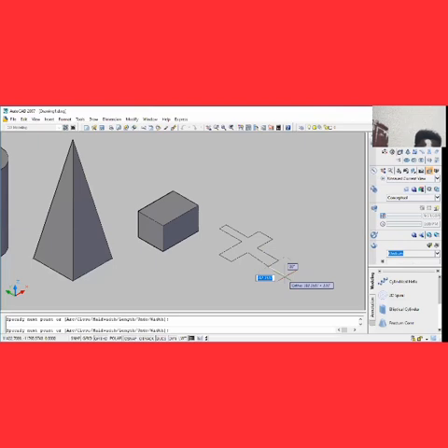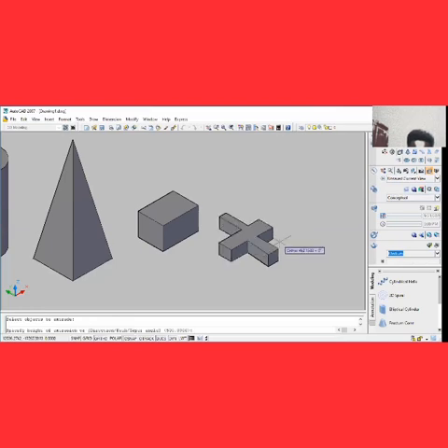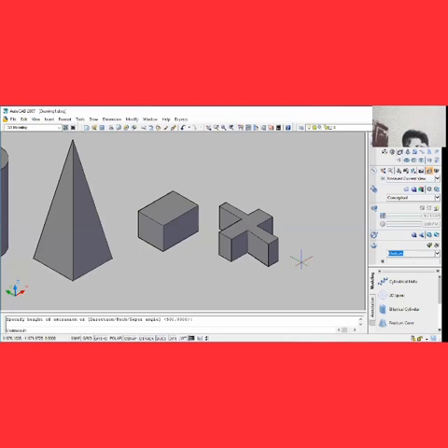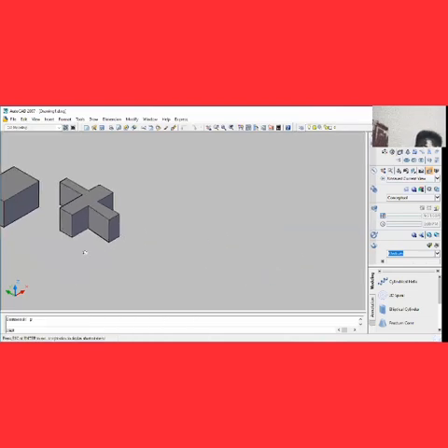So now you can use your extrude command on this. All you just need to do is come to your extrude icon, left click on it, and then select the object you want to extrude. Left click on it, then right click outside of it. Then choose any height you want. So if you're okay with it, you can just left click, and that is it. So that is your extrude command. So let's also move it to the left, P, enter, and then we'll drag it, left click and drag to the left, escape.